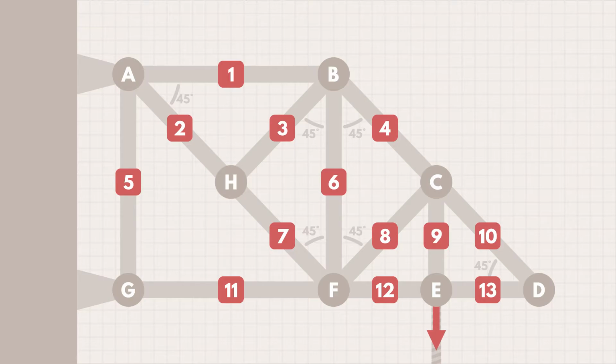There are two reaction forces, or one per attachment point. Since the attachment points are pin joints, these reaction forces have both X and Y components. If the truss were three-dimensional, they would have X, Y, and Z components. Note that we usually assume that truss members are massless, so gravitational forces acting on them are ignored.